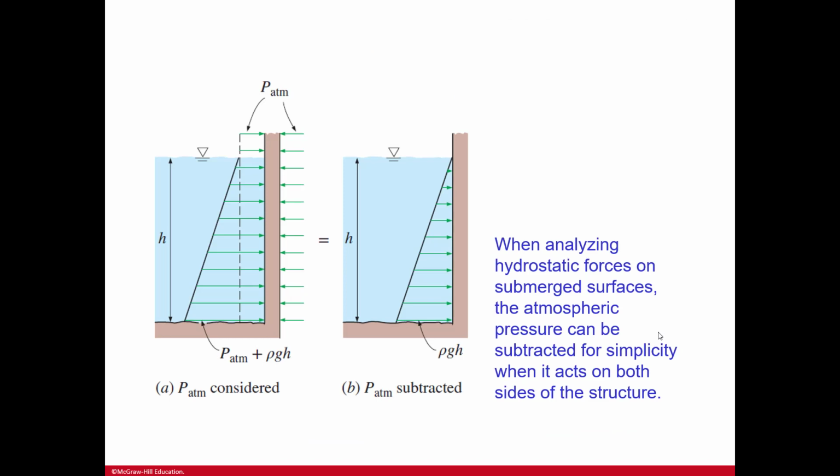Here it looks a lot like the same. When analyzing hydrostatic forces on a submerged surface, the atmospheric pressure can be subtracted for simplicity when it acts on both sides of the structure. And also, when you go deeper and deeper into the working fluid, the pressure is going to increase.